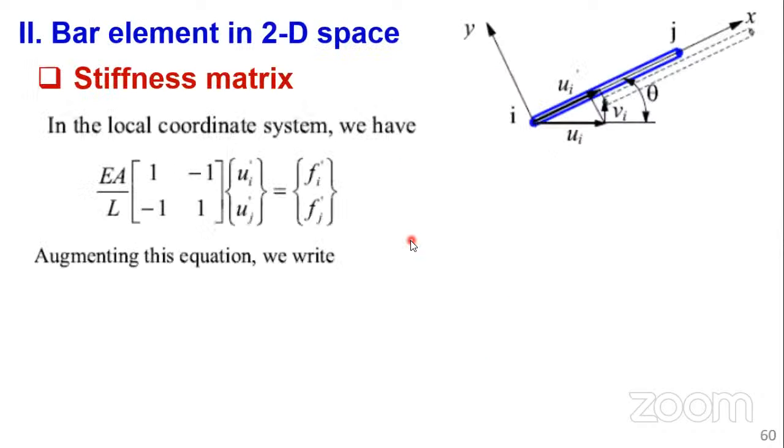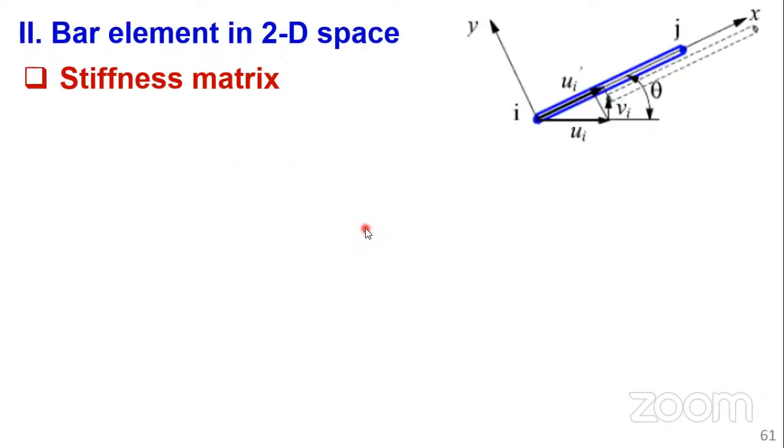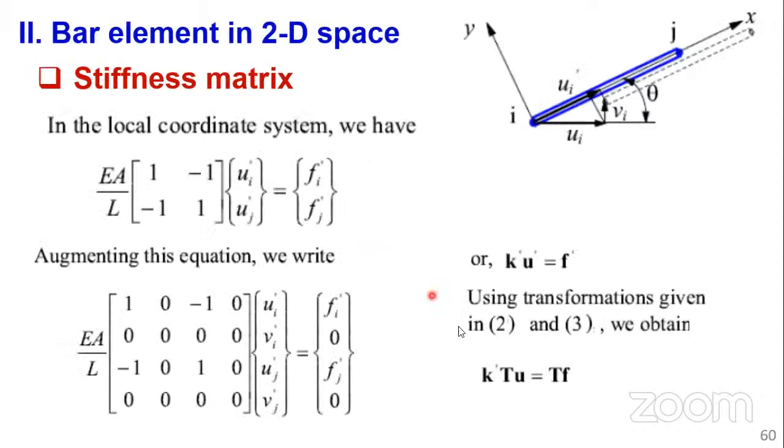All right. So we move now to this part. So we are saying, if you look at this equation, we know at the back of our mind that the form of our stiffness matrix, of our finite element equation, is like this. If we can eliminate this T from this side, then whatever you have on this side, you have U, whatever will be formed here will be equal to the K in the global coordinate system.